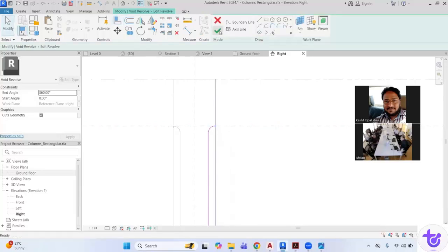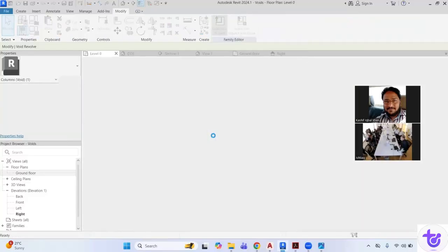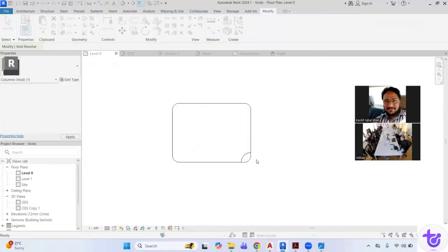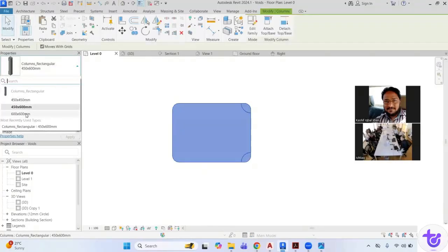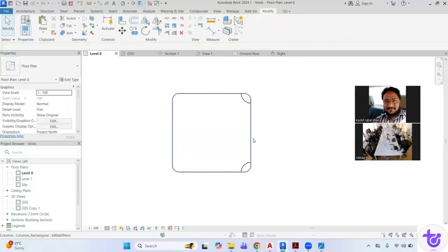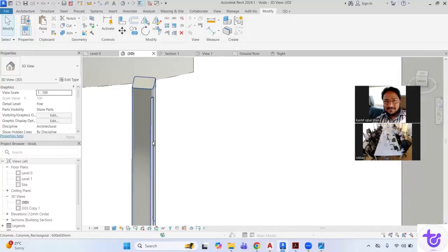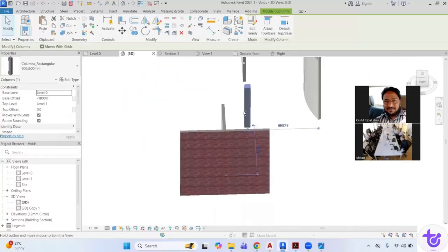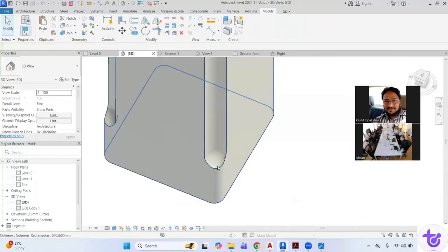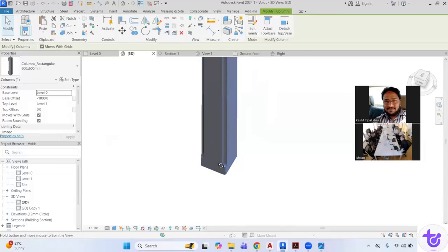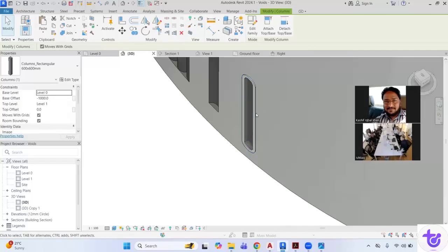And then if I load this in the project, just check if I change the size of the column, yeah, it is properly fitted. And at all corners. At 2 corners I have done. You can also do it in the rest of the 4 corners. Any difficulty in this? Because it's been done again with the help of the revolve, the same way it was done in the curved shape wall.